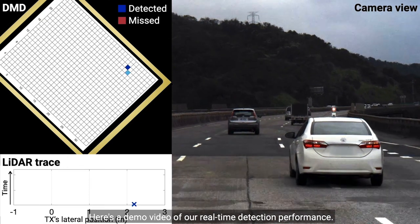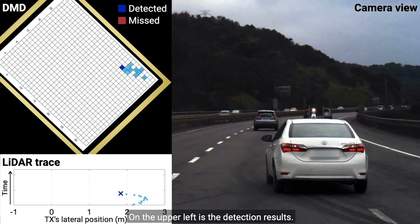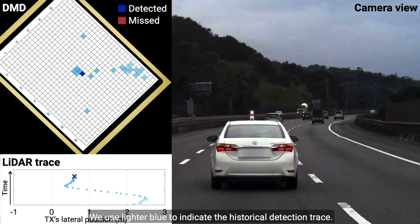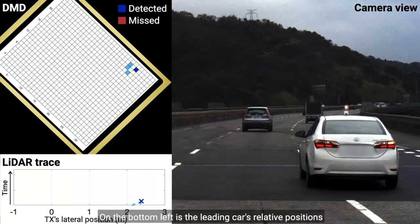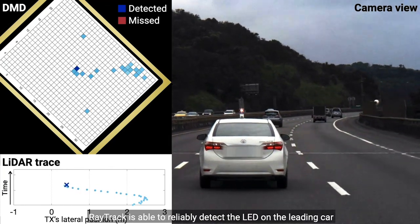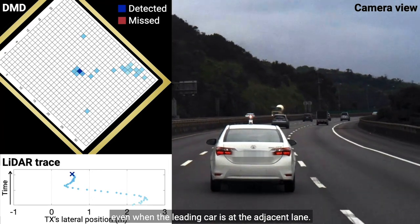Here's a demo video of our real-time detection performance. On the upper left is the detection result. A dark blue block means a correct detection, while a red block means a missed one. We use lighter blue to indicate the historical detection trace. On the bottom left is the leading car's relative position to the following car. As you can see, RayTrack is able to reliably detect the LED on the leading car throughout the lane changing maneuver, even when the leading car is in the adjacent lane.